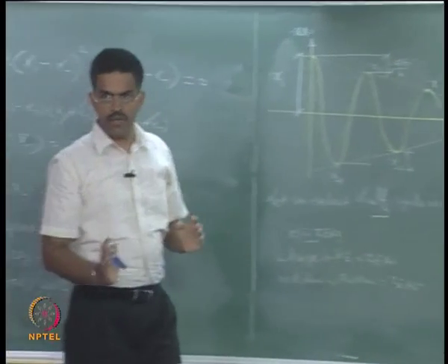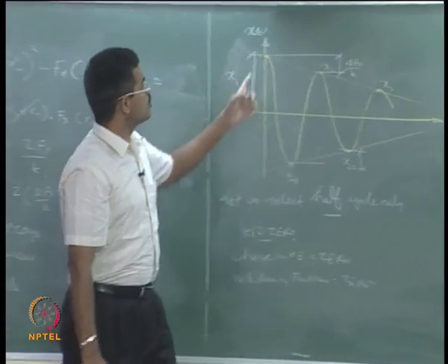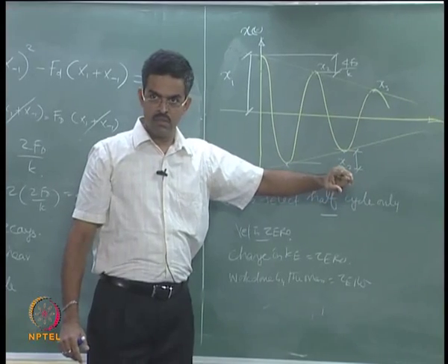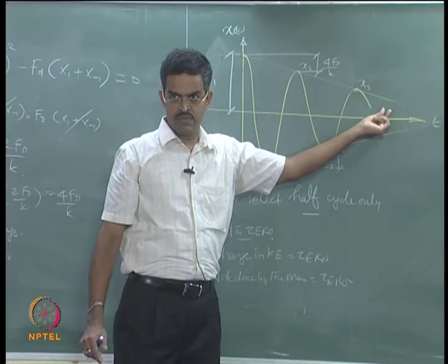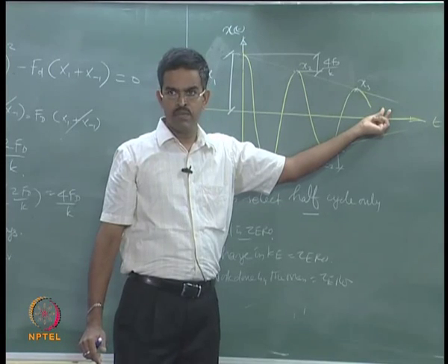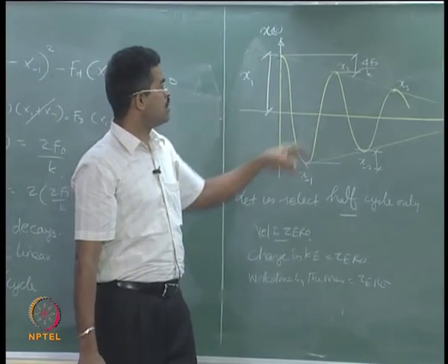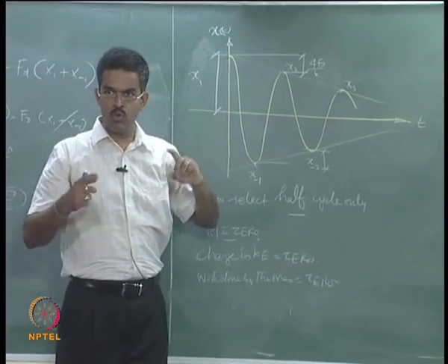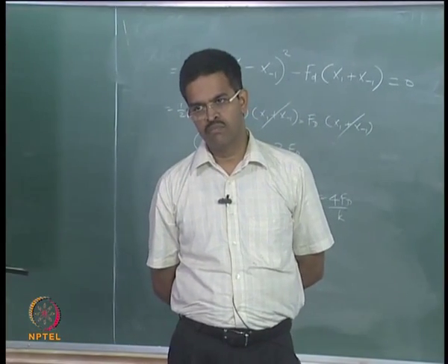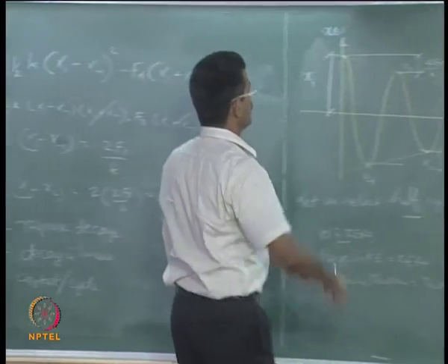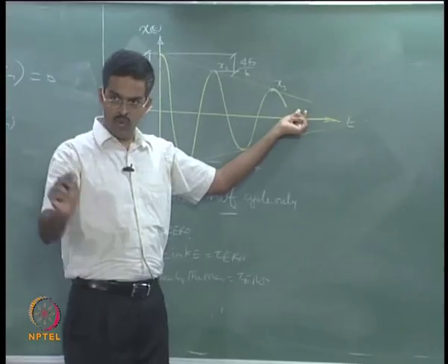So if you want to really reduce the response from x1 to xn, you have got to undergo so many number of cycles to bring down the response from this peak to the desired value of your choice. Okay. So what do you understand by making so many number of cycles? You are alternately creating a response which will induce a fatigue problem into your model, because the model has to undergo n number of cycles before it reaches the desired response of your level.